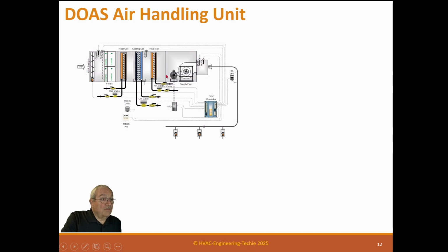So these units take the burden of dehumidification, and the burden of high temperature drop or high temperature increase from outside air, and normally we just provide 80-degree air to the air handler, which is supposed to be equivalent to return air, so that these units never see the outside air burden. Only this unit sees it. And why is that? Because all these special controls and things within this unit are expensive.